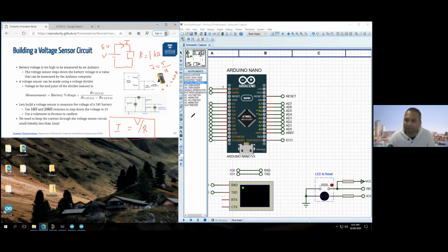Okay? Now, the same is true if you want to work out the voltage: you multiply current by the resistance and you get the voltage. Right? In this case, if you had 0.005 amps going through 1 kilo ohm, you get 5 volts. Which also agrees that if you go around a loop, the voltage has to drop down to 0.